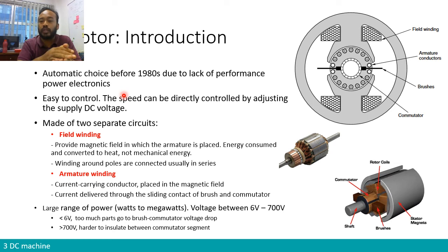Inverters, as we are going to look at later in the topic of AC machines, induction machine and synchronous machine, are that part of switches that create those AC controllable signals. Due to the lack of that, it was easier to control just the speed of the machine by delivering different amplitudes of DC voltage to the machine. Therefore, the choice is quickly done. We industrials usually don't even think about it. It is an automatic choice to pick a DC machine with commutator to use in different applications.